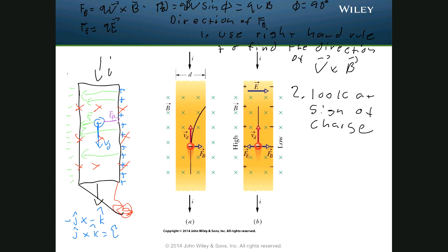The reality is, your theory of positive charge carriers says that you should measure a positive voltage here. But when you put the voltmeter to the test, you get the voltage you were expecting, but it's negative. So what that means is that your initial assumption is incorrect. The charge carrier is not positive.